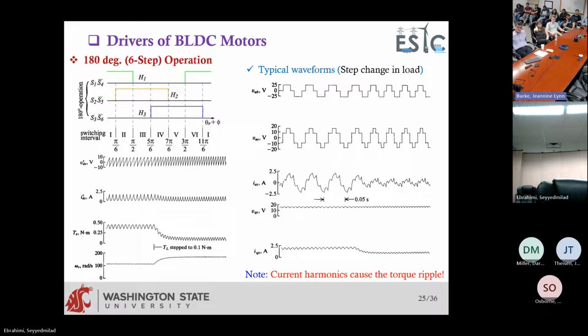It means that you want to apply some force to rotate the shaft, but it loses it and then makes it harder. So instead of rotating smoothly, it tries to push it faster, then release it, push it faster, release it, instead of applying a constant 0.6 Newton meters, and it causes vibration. So these humps, sinusoidal on top of a DC value, are called ripples. And the vibrations are what we want to avoid, because those torque ripples cause vibration.